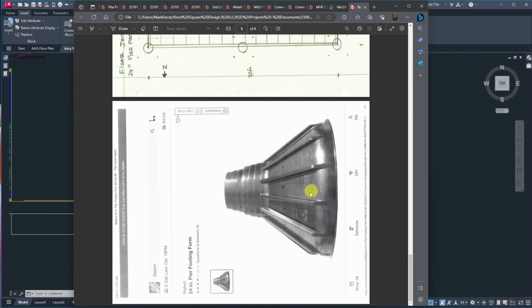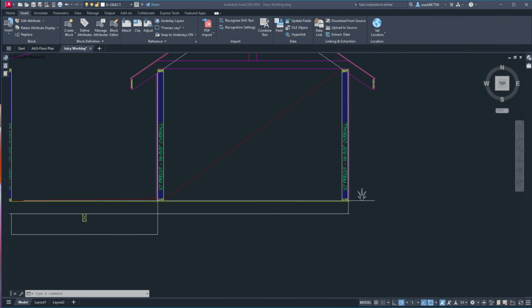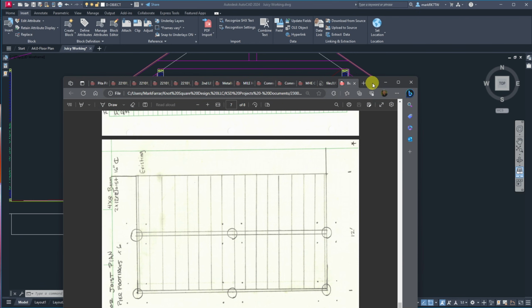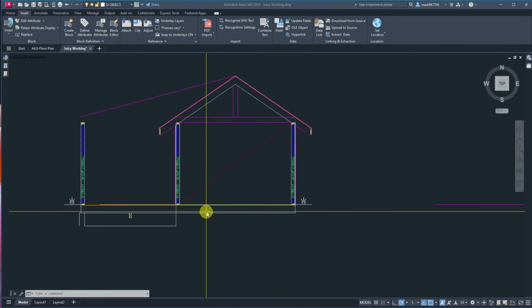What they wanted to do is put these Bigfoot pier footings in. It's just a leave-in-place form. Stick it in, pour concrete in it, forget it. And maybe that'll be our plan, but we've got some things to deal with here, and that has a lot to do with how we're going to get these boards in there and have the clearance to the dirt.